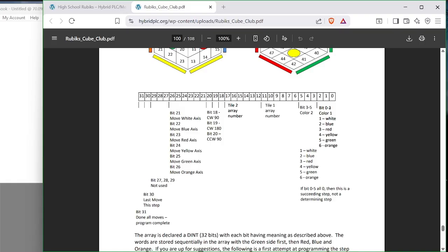They just said, we ran out of memory. Well, what are you going to do with that? It's kind of like, okay, you should plan a different way. But I've been very skeptical ever since then of using too much data. And one way of spreading everything out is giving every data a different type and all that kind of stuff. Memory's cheap, but they've got a limited database area in these PLCs. So again, that's kind of where I ended up being scared to death to do. So I cram everything into a 32-bit word, a DINT, D-I-N-T word, and then go from there. Okay?